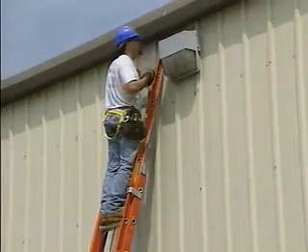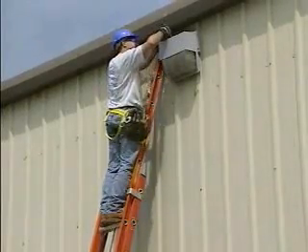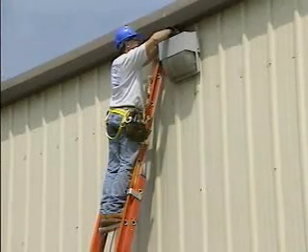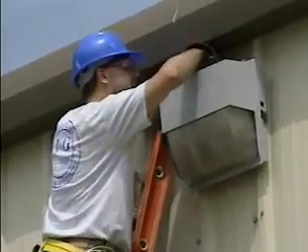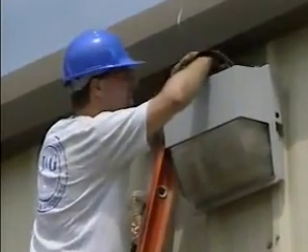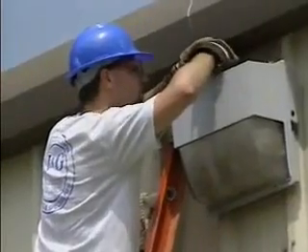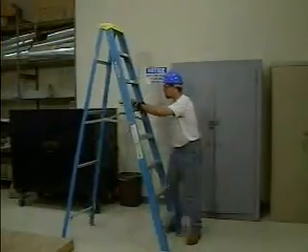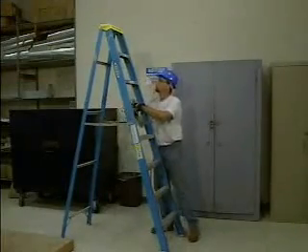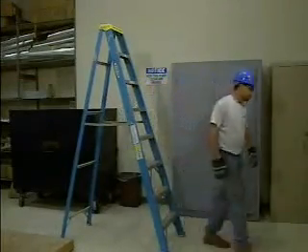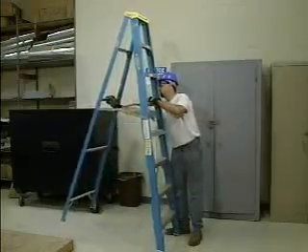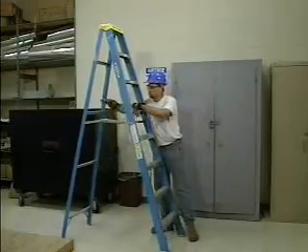Ladders are commonly used to enable personnel to work in elevated locations, but anytime work is performed above ground level, there's an increased risk of an accident. To reduce the chance of an accident associated with using a ladder, some basic safety guidelines should be followed. In this part of the program, we'll identify some of the basic safety considerations that apply to straight ladders, extension ladders, and step ladders. We'll also look at how to select and use the proper type of ladder for a job. Ladder safety begins with choosing the proper type of ladder for the job.